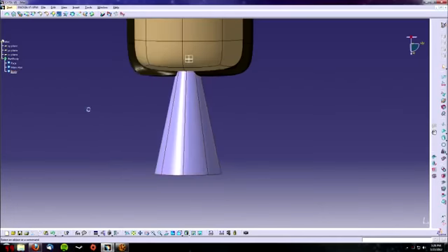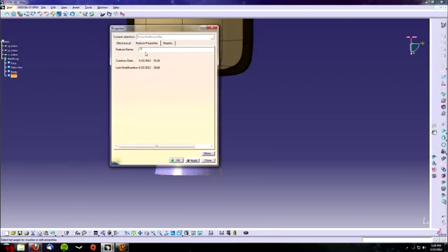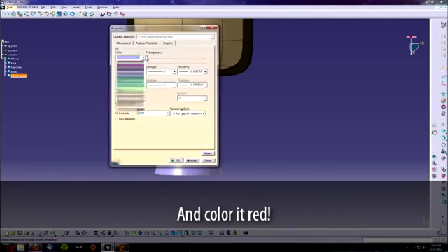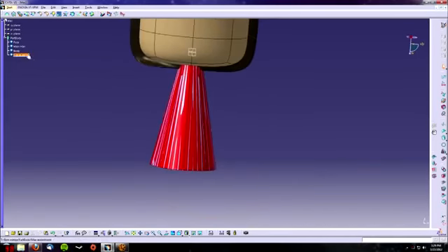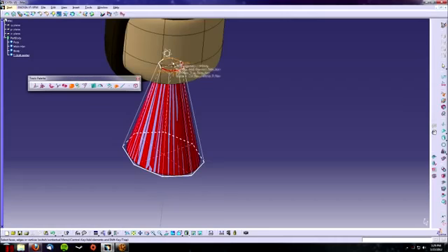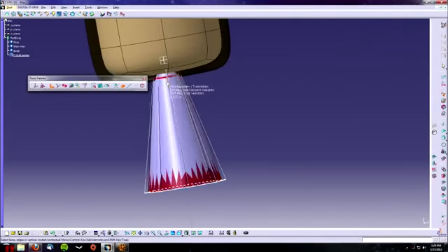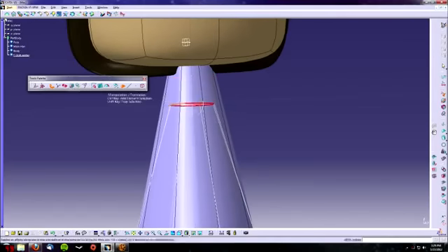To make his t-shirt, what you need to do is go ahead, copy and paste the body piece that you just created, copy and paste that into your part body. This will make a completely similar basic body shape where his current body is. And select the top surfaces again and move them back and move it down a little bit. This will create a little bit of distinction between the top of his shirt and where his neck is.